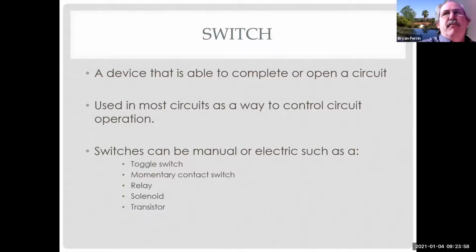You asked, is the amperage the same for AC and DC? Yes. The rule that governs amperage is the same. Ohm's law is the same. Now keep in mind, my AC current has 120 volts or 240 or whatever. So I have higher voltage, but yes, I can figure out my amperage the same way through resistance. It's the same exact principle.